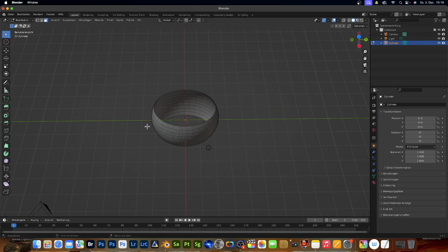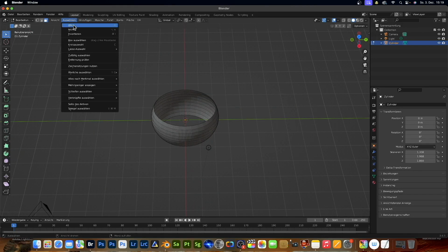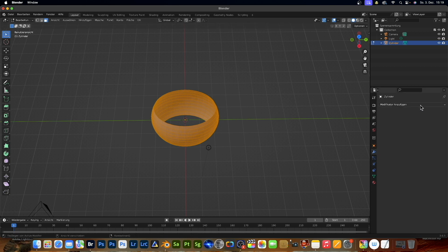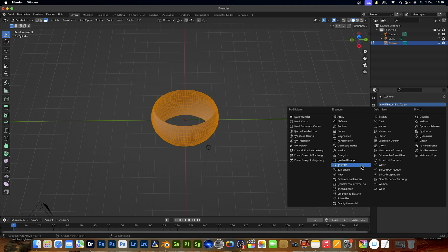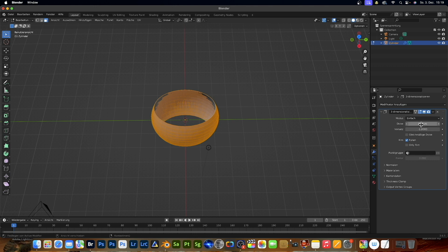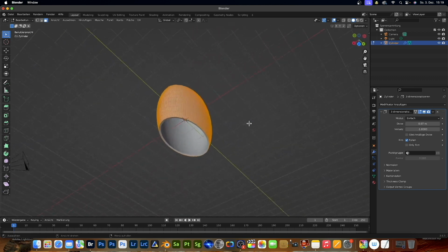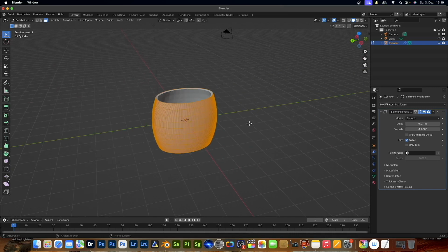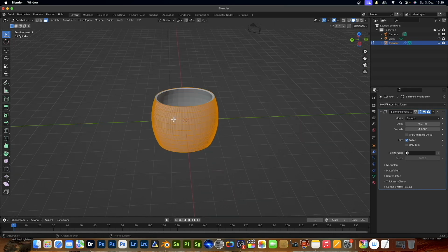Now it's a pipe. And I go to select all, and then I go down here under my wrench, add modifiers, and I want this whole thing to be a bit three-dimensional. So I click here once and say I would like to have a thickness in my surface. Then the whole thing has become a bit thick now. We see it looks like this now. You can't even imagine that a cave will come out of this, but I can promise you a cave will come out of it.